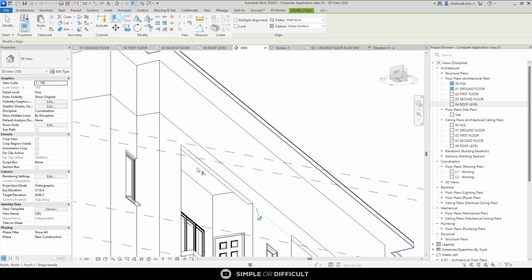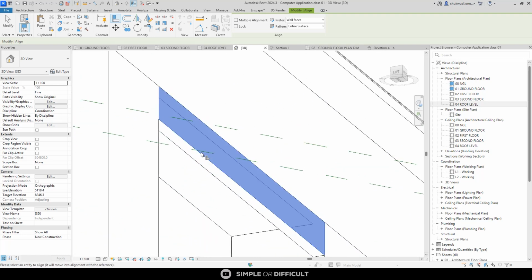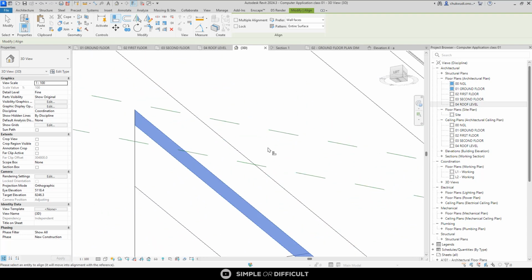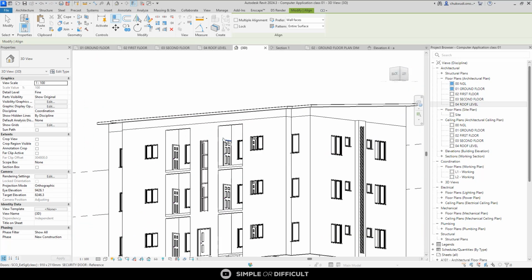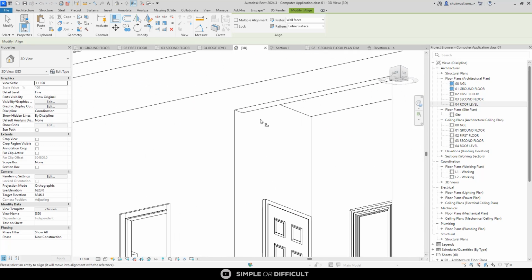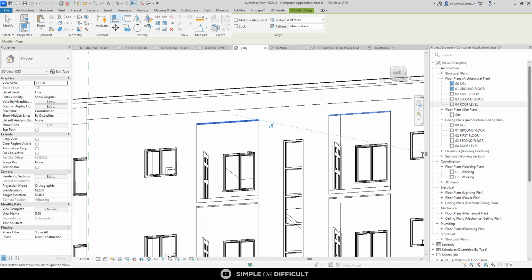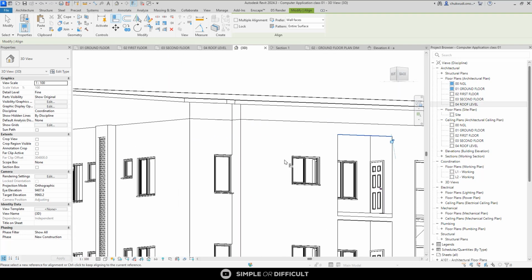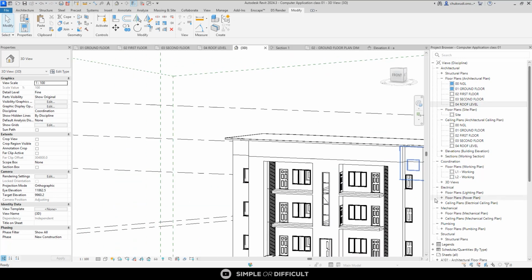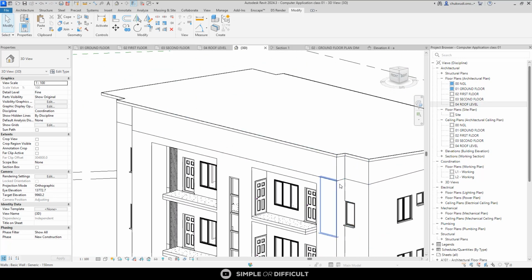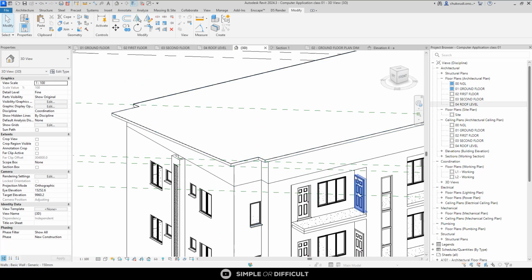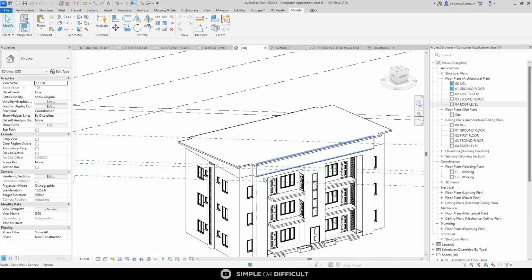Then I'm going to bring this one down. This same stuff, I'm going to do it for the back side as well. So I'm going to hold down Control so I can do this more than once. So Control, click here. So it's going to bring it down for you and make everything 450. Now I want to do a design that will go from here down to this side, flushing from this area. So how do I do that? I do that using the sweep tool.